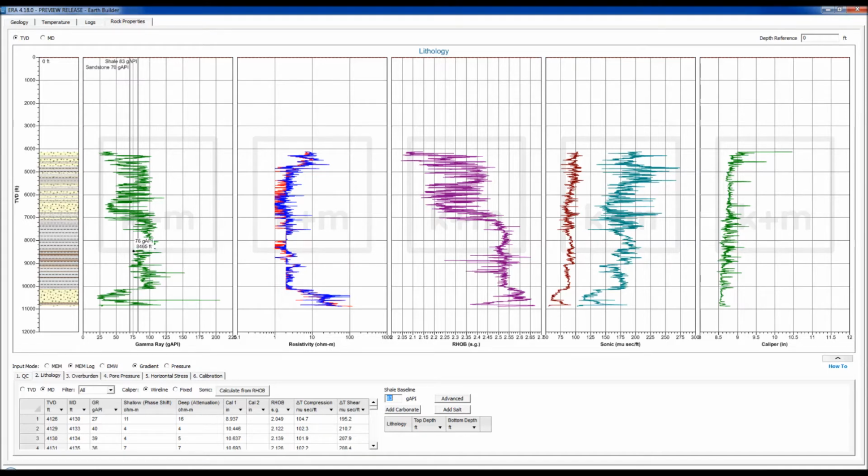And it's 100% not shale to the left of this other line, which is what we call our sandstone baseline, although it's maybe not a totally accurate term. We should just call it not shale baseline, and that's where we define our clean formation. So you could take it to the extreme and say, okay, only extremely clean gamma ray intervals are what we would call clean sands or clean carbonates, clean salts. But what I usually do is adjust that sandstone baseline to be about 10 values less than my shale baseline.